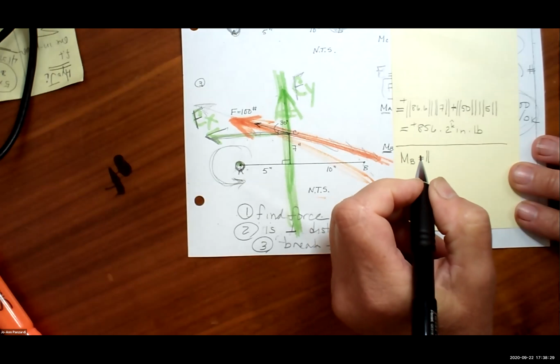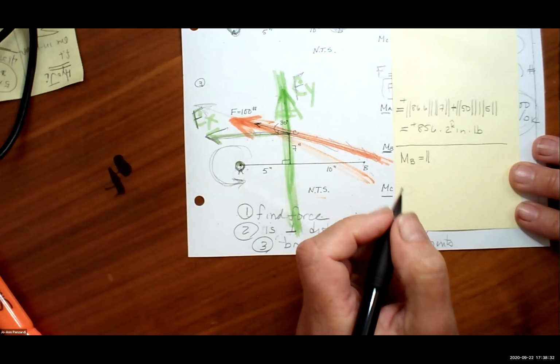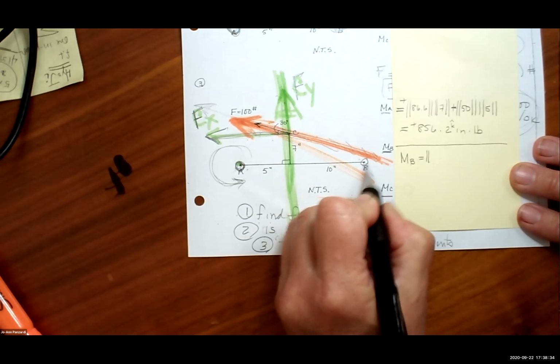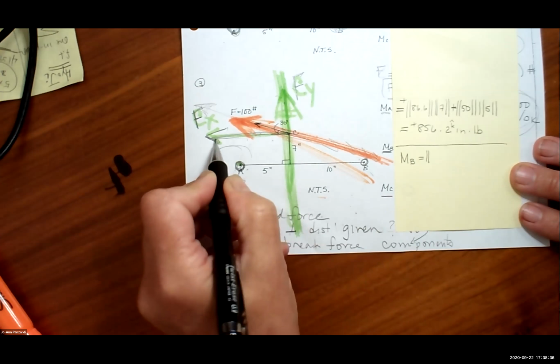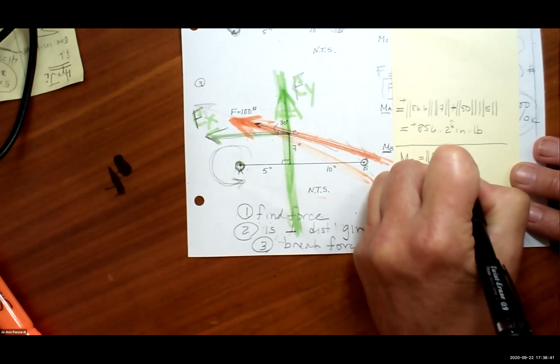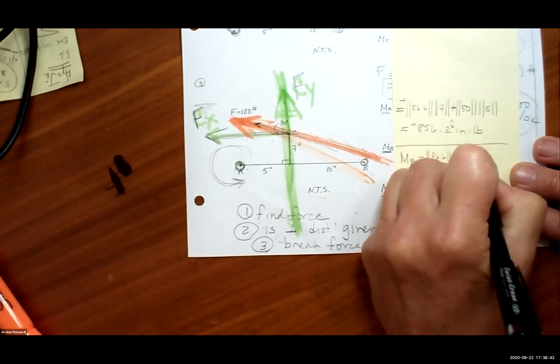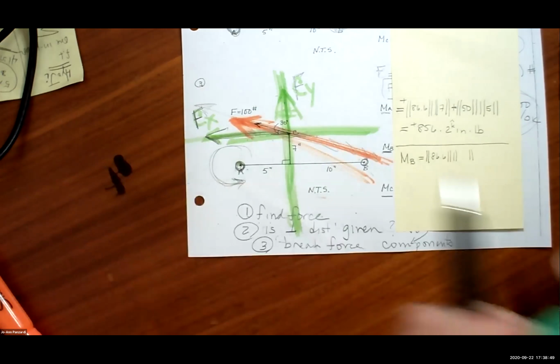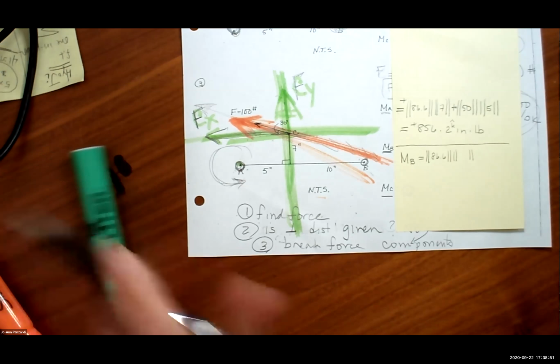So I am up to Liam. Liam, I'm calculating the moment about B due to Fx. So Fx is 86.6. What is the perpendicular distance from Fx to point B? 7 inches. Great. Positive or negative? Fingers in the direction of the force. Palm goes towards the point I'm finding a moment about. Positive or negative? Positive. Great.